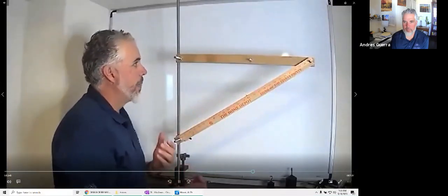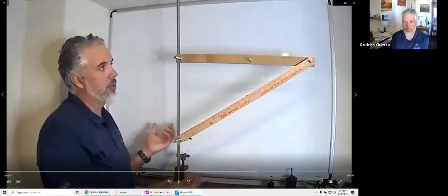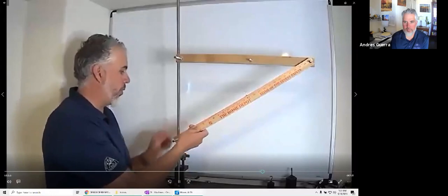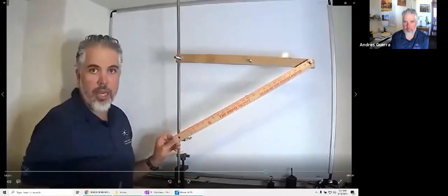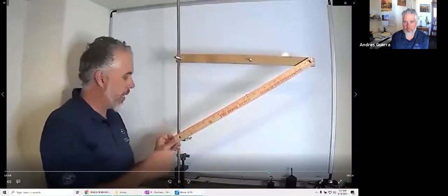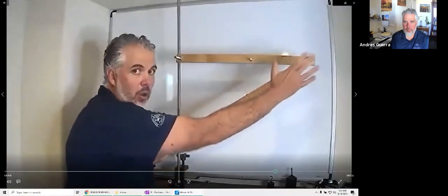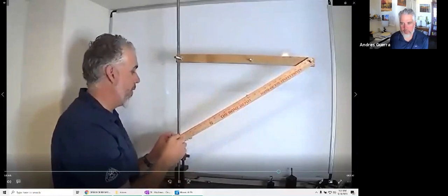And then we can also start to think about our options for free body diagrams. We could do a free body diagram of the whole thing, in which case I would just pull out the pin here. I would pull out the pin up here, and leave everything intact over here if we draw an FBD of the whole thing.